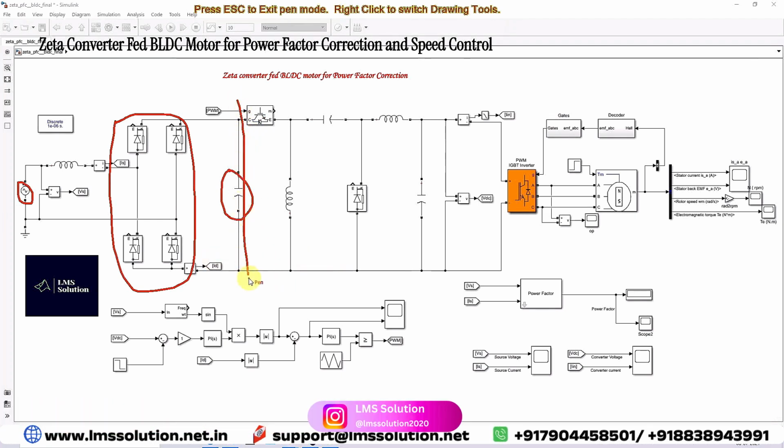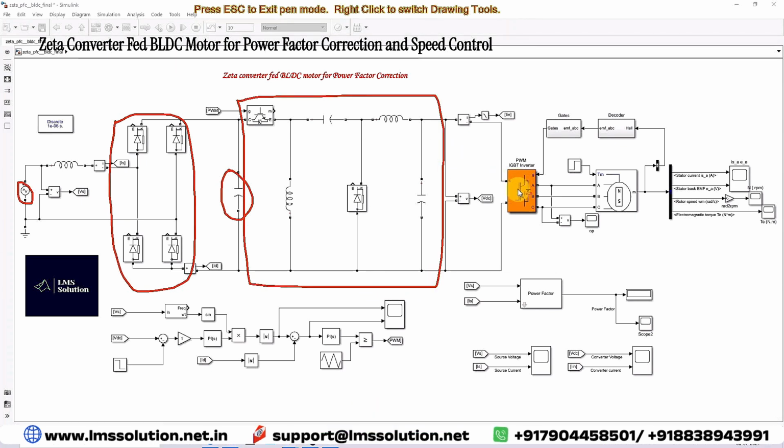This arrangement is known as the Zeta converter, and the Zeta converter output is connected to the voltage source inverter and the BLDC motor. The BLDC motor is controlled by means of Hall sensor position. The Hall sensor position is converted into gating pulses by using this arrangement. The pulses are given to the voltage source inverter to control the speed of the BLDC motor.